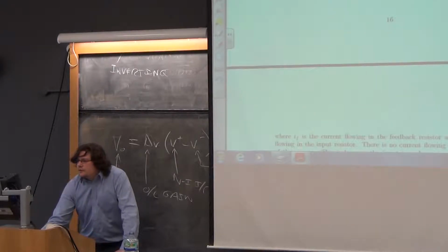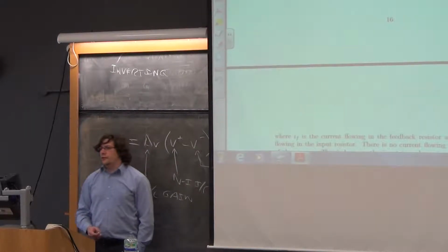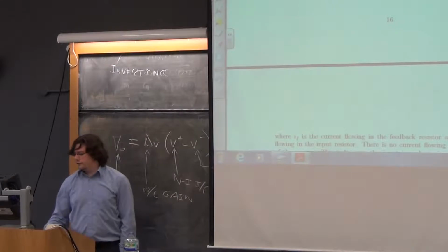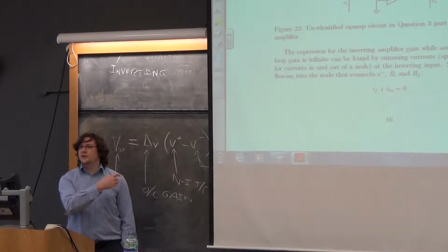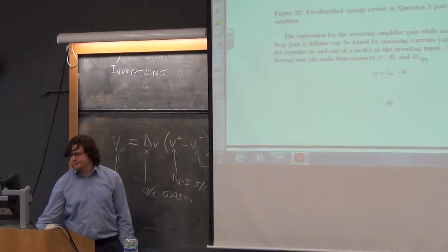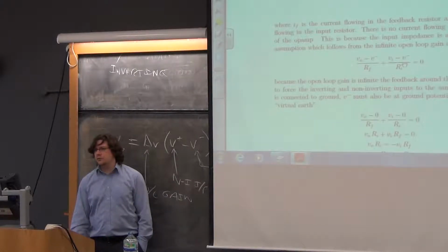So yeah, you sum the equation 30. You sum the currents at the input node, and you say if you draw any arrows the way that I drew them. Okay, I didn't draw any arrows, but you can work out from the equation which way I thought the arrows were going in my head when I drew the diagram. And then you substitute in the voltages and yep.